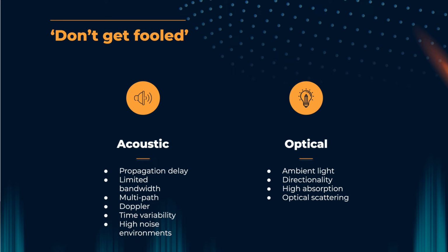If it's deep waters, like the deep oceans of the Pacific Ocean or the Atlantic Ocean, it's not much of a problem. But in a pool kind of environment where you will be working, one of the first things you need to be mindful of is reflections. If you blast out at full power, it's going to reflect off and come back, and at the receiver it will receive many things, and then you will have collision. This is a standard problem with wireless technologies. It's not just an acoustic problem. Any wireless system will have to have some kind of collision detection and avoidance system.